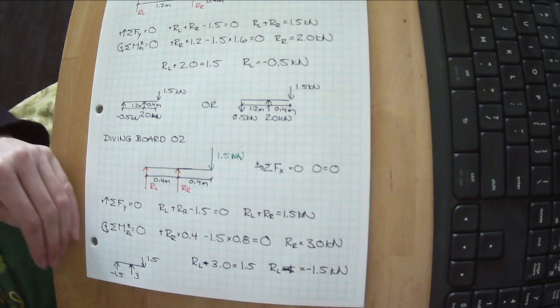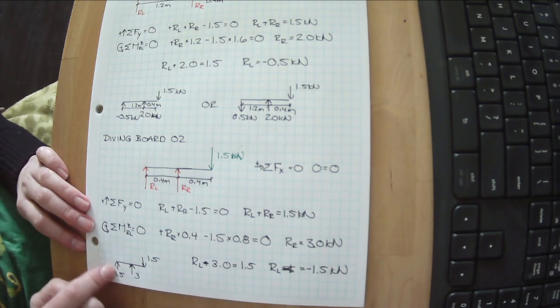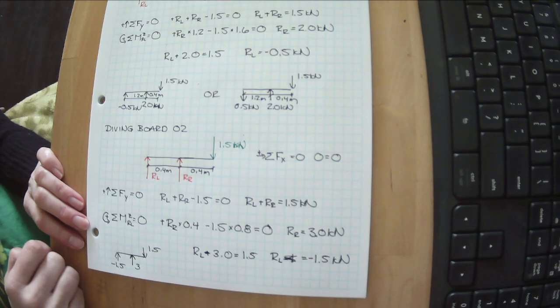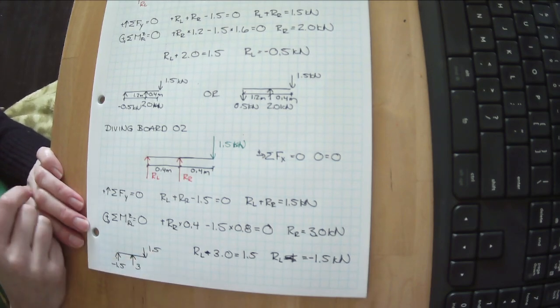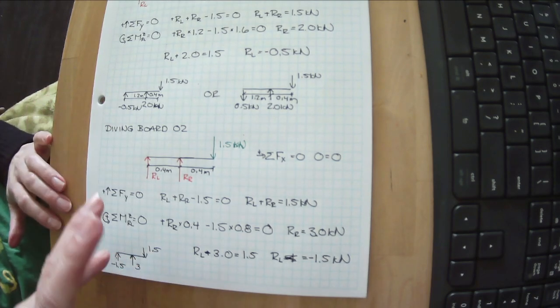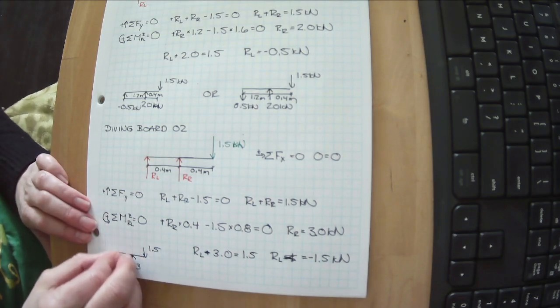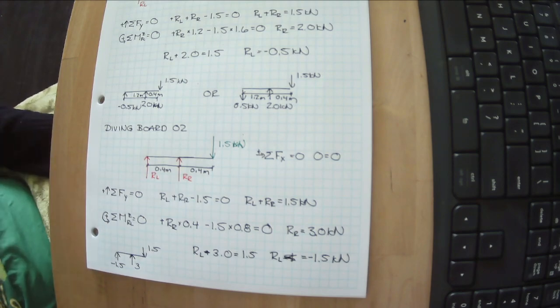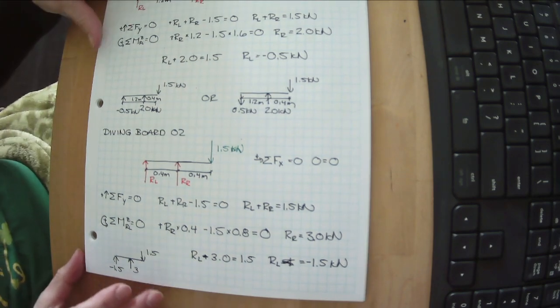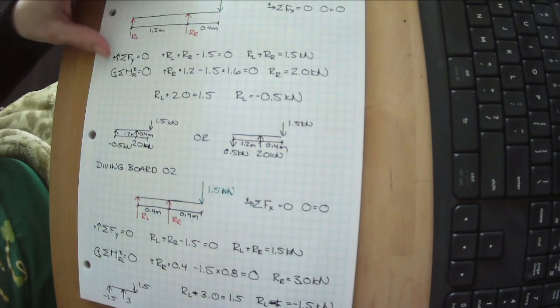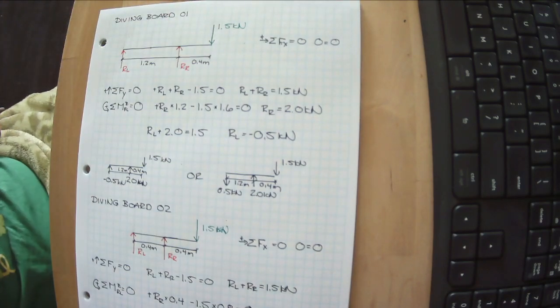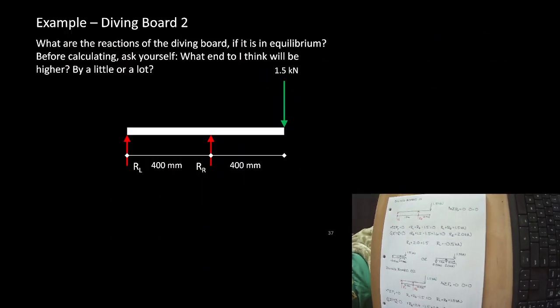So shortening the backspan increased our reaction forces. Even though the load on the system didn't change, this tendency to want to spin increased our forces right here. So that's kind of interesting. It seems like we've got some cool tricks now to be able to solve for some of these reactions.